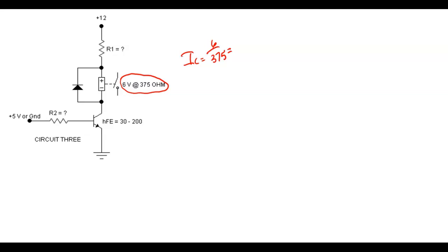So this is our series circuit. This is the series circuit over here. There'll be no current flow through the diode. Why is there no current flow through the diode? Well, the cathode is pointing toward the plus, and the anode is pointing toward the minus. So this guy here is reverse biased.